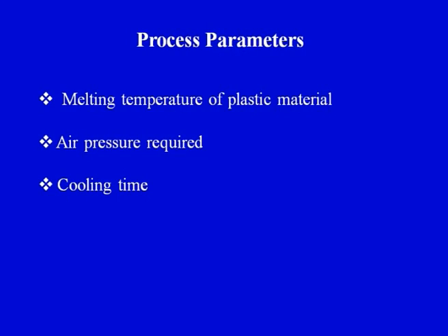Now what are the important process parameters in blow molding process? As you can see, melting temperature of the plastic material, because although it is not melting, we should not write melting, but the temperature at which it can be deformed. So the temperature at which the plastic can deform and it can inflate and adhere to the walls of the mold, that is the temperature which is very important. So that has to be taken into account.